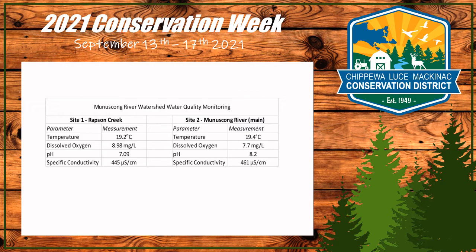When materials ionize, they become ions and they become charged, which in turn increases the likelihood to pass electrical current, which in turn increases conductivity. Again, the cause for the difference is probably runoff in the area. Both measurements are close to each other. We're talking just around 20 microsiemens per centimeter difference, so it's not a huge difference.